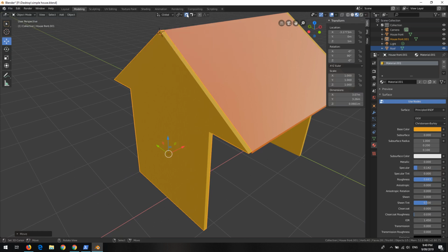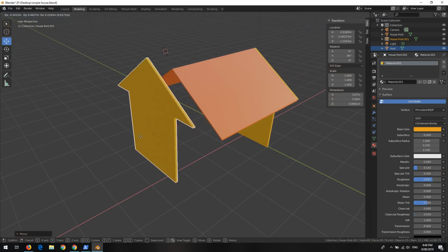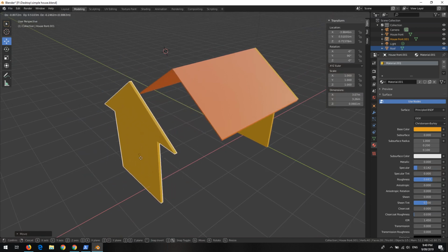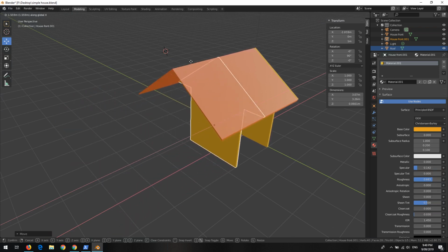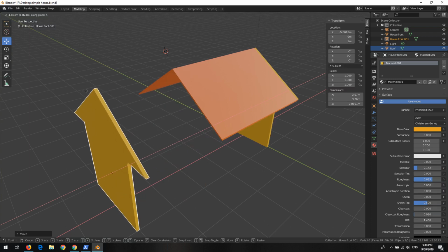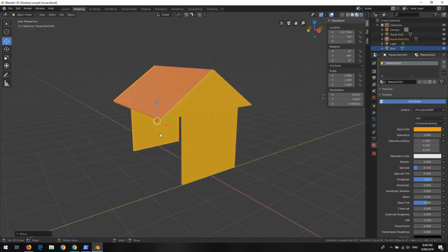Let's turn it off. Again, when you want to move, press G, and you can constrain again to X by pressing X and then move around, because the snap is off. If you want to cancel any operation, just right click and it takes us back.